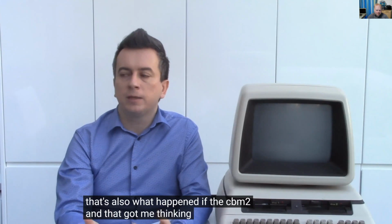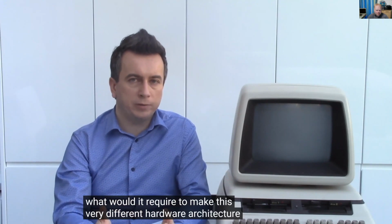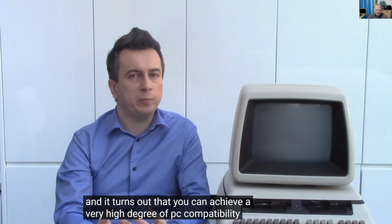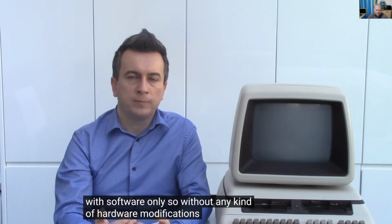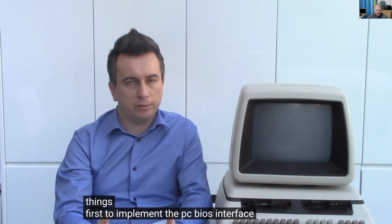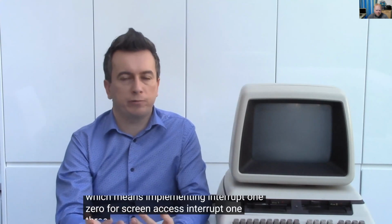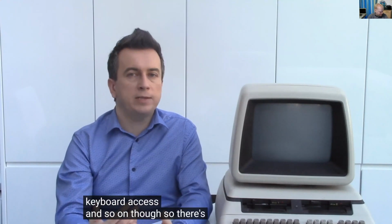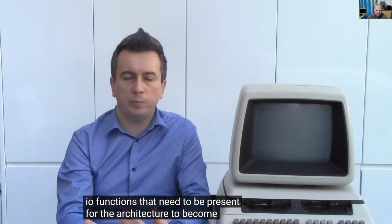And that got me thinking, what would it require to make this very different hardware architecture PC compatible? And it turns out that you can achieve a very high degree of PC compatibility with software only, so without any kind of hardware modifications. And for that, you just need to do two things. First, to implement the PC BIOS interface, which means implementing interrupt 10h for screen access, interrupt 13h for disk access, interrupt 16h for keyboard access, and so on. So there's around 30 or 40 I/O functions that need to be present for the architecture to become PC compatible.